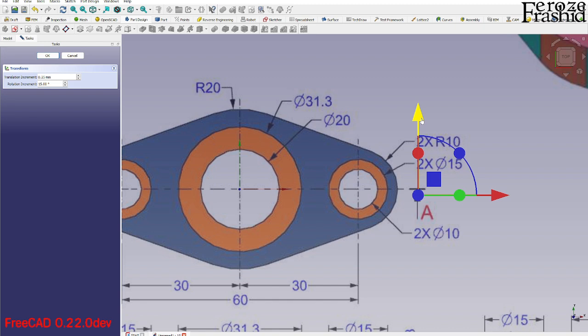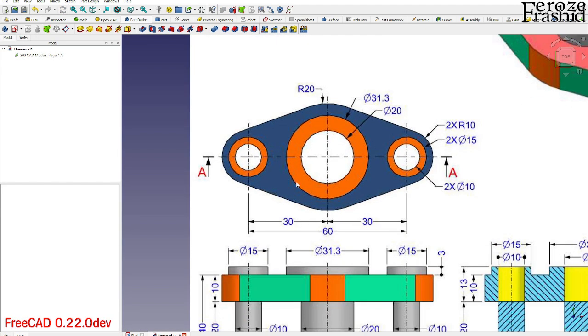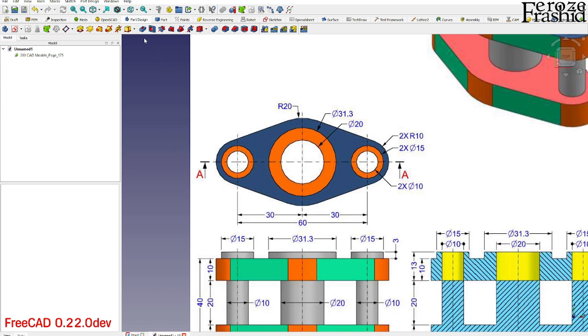Let's go ahead, bring in the axis cross and then relocate the image at the center of this center hole, and then take the axis cross away by pressing AC on the keyboard altogether. And now we are ready to draw on XY plane.